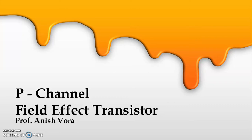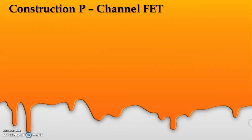In this video lecture, we will study the P-channel type of field effect transistor. Before we start the construction of the P-channel field effect transistor, we know that a field effect transistor is a semiconductor device in which conduction of current through the channel is because of majority charge carriers. FET is a unipolar semiconductor device in which the control of conduction of current is done by an electric field, which is generated by reverse biasing the gate.